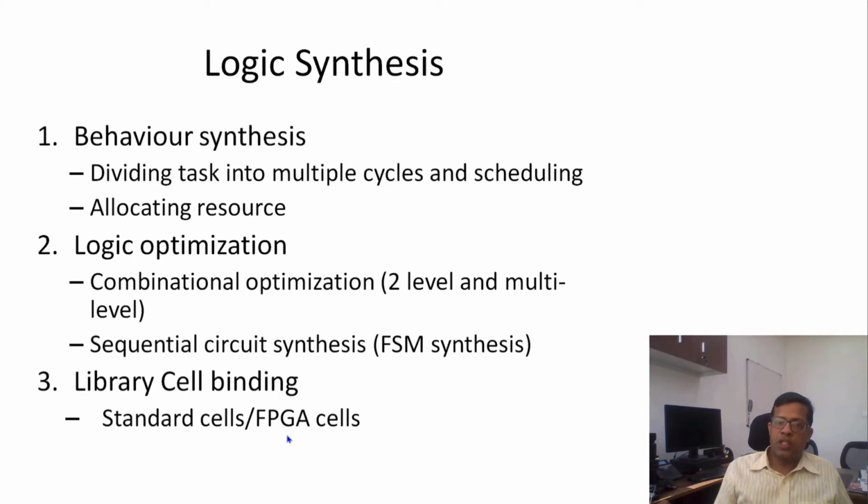the option. See, in the standard cell library, we have seen the maximum number of inputs to a cell, a gate, is 4. So if more inputs are there, automatically our two level circuit will also become a multiple level circuit. That is why combinational optimization for multiple level is more suitable.